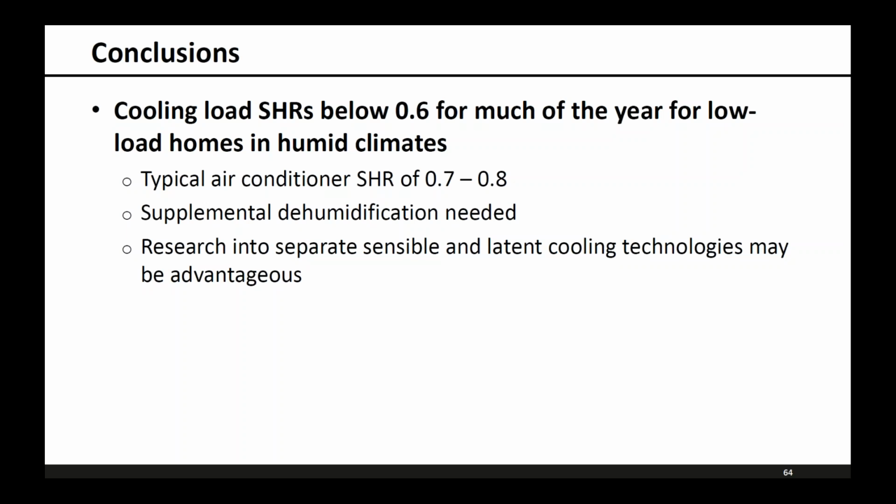So in order to make that up, some supplemental dehumidification would be needed, or the homeowner would resort to adjusting the set point down. And due to this changing cooling load SHR, additional research into separate sensible and latent cooling technologies may be advantageous as we increase home efficiency further.